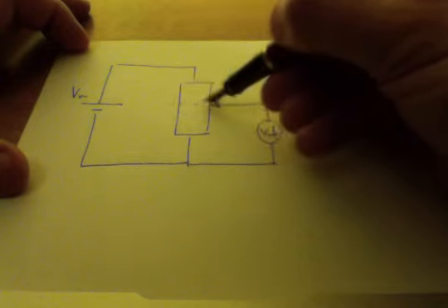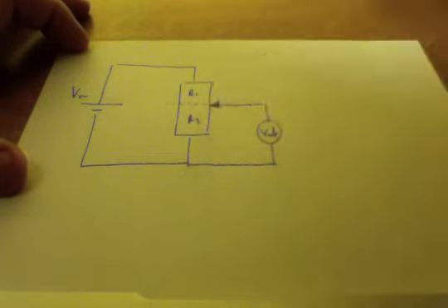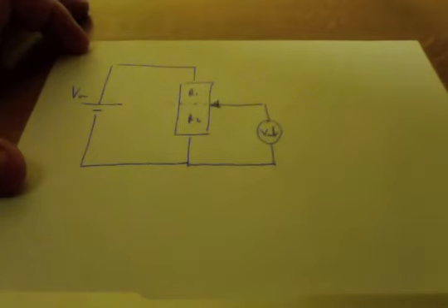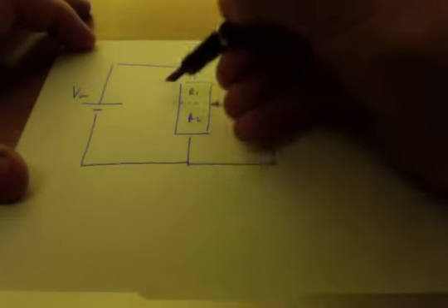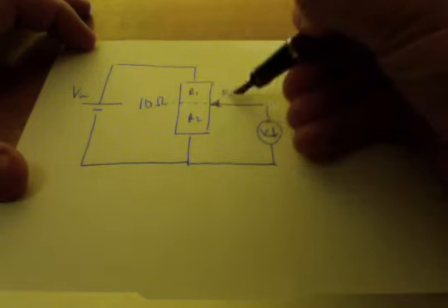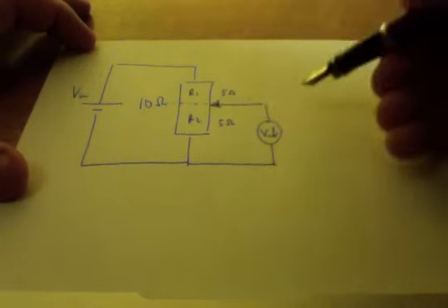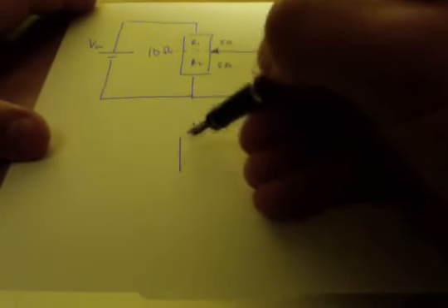In other words, you're dividing this total resistance into 2 resistances. Now the reason why that's so useful is because if this were, say, 10 ohms from top to bottom, and you cut it halfway, you're creating 2 5 ohms, which means you get half of the voltage and half of the voltage.